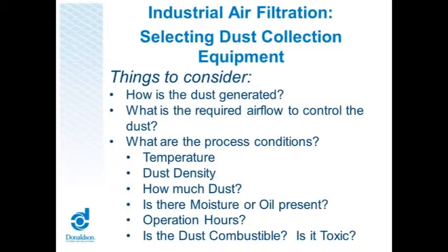Also, is the dust combustible? I know we talked about this a little bit with NFPA, but that is becoming a big, big emphasis, and people are seeing that more and more as we need to know what that dust is, what a KST value or a Pmax of that dust is so that we can handle it appropriately and make sure that OSHA is satisfied with what we're doing.